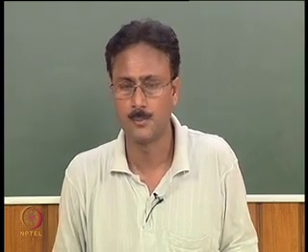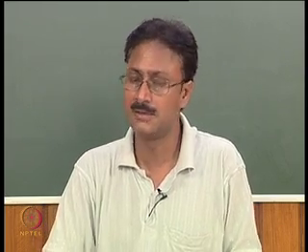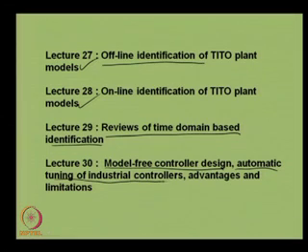Controllers can be designed in two ways, either model based or model free. In the model free controller design, plant information will be acquired online, and that information will be fed to the controller simultaneously when the controller is in action. That is known as model free controller design. And we shall also see automatic tuning of industrial controllers and their advantages and limitations in lecture 30.